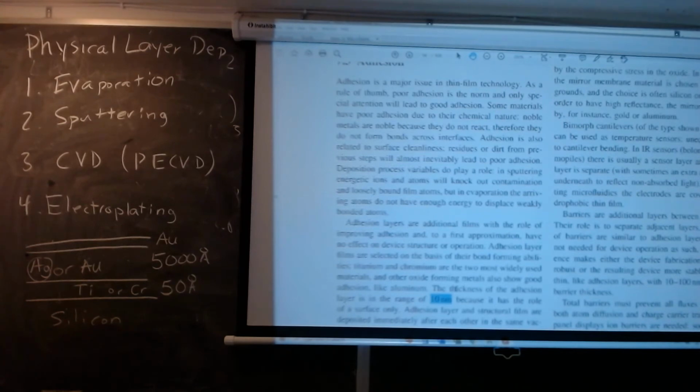And then if your metal contact has to be very thick, you can use silver and deposit microns of silver by evaporation. And then to form a nice pristine surface that doesn't oxidize or tarnish, you can then put a few thousand angstrom layer of gold on top of that, and that kind of acts to seal the contact. And the point is that I have found that you don't need another adhesion layer between the surface of that silver and the top gold layer.